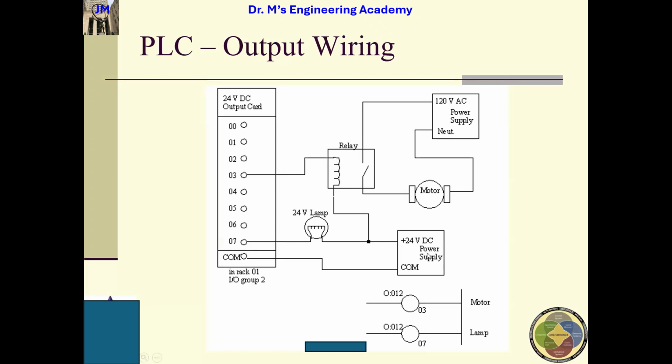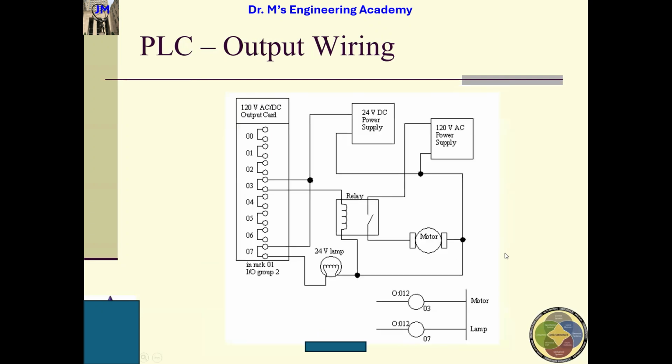As I said, the vendor has done this for us. If we want to do this from scratch, you need to buy a 24 VDC supply, or use the same power supply as the PLC, and then connect it to the input card. So the vendor has done this for us, and we are standing on the front side. Otherwise, you need to wire them together. Questions?